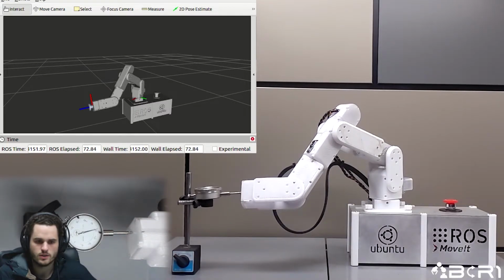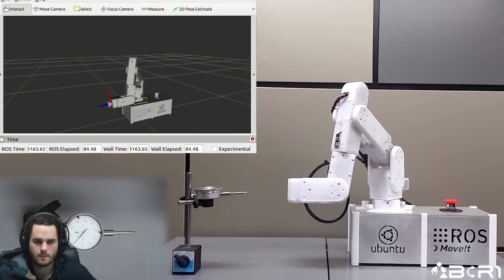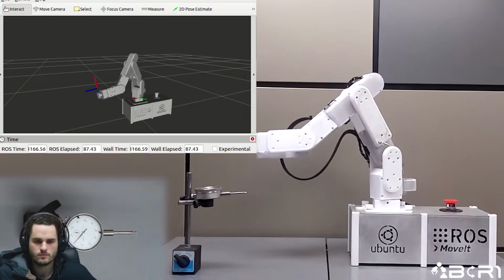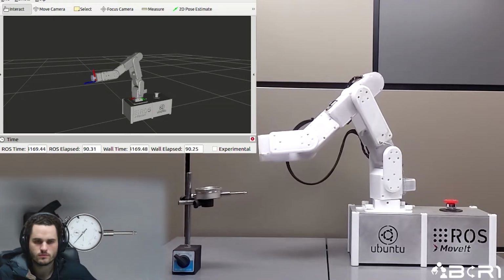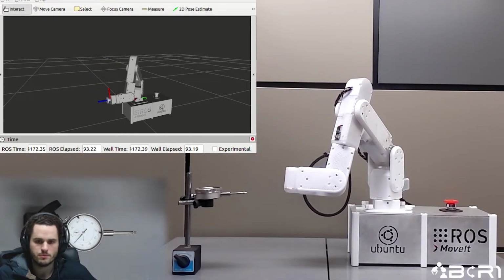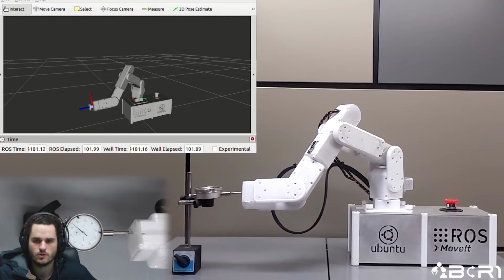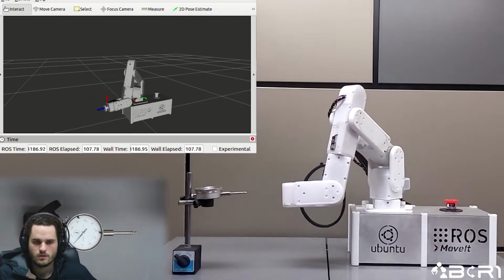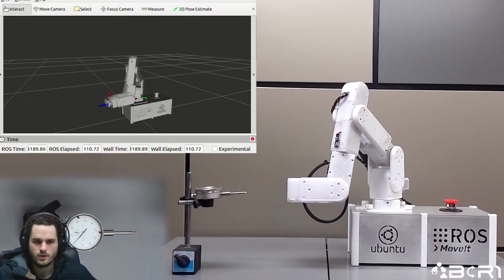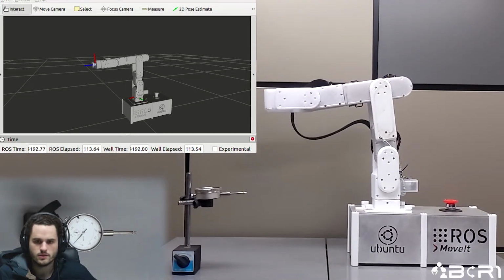So here it's probing the dial indicator. It'll hold this position for 8 seconds for a reading to be taken before returning back to its home position. For demonstration purposes, this was conducted 4 times, but for experimental analysis, this was repeated for 30 cycles. This same method was applied to the Y and Z axis.